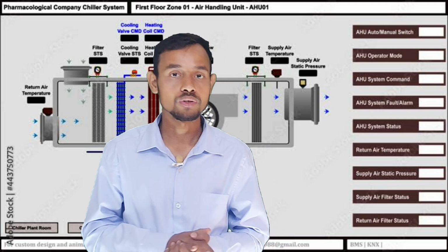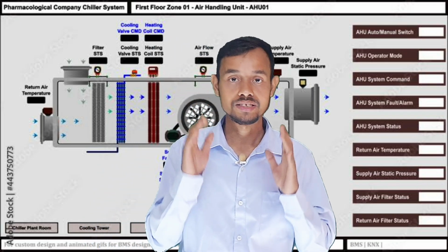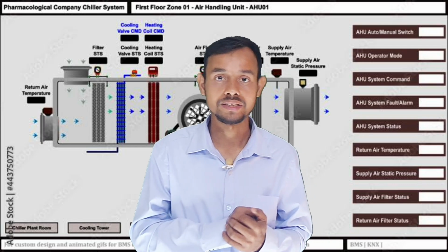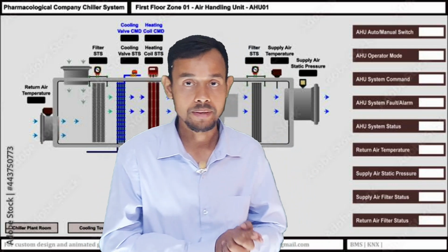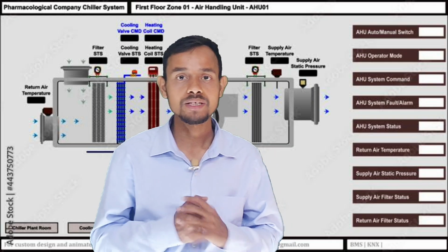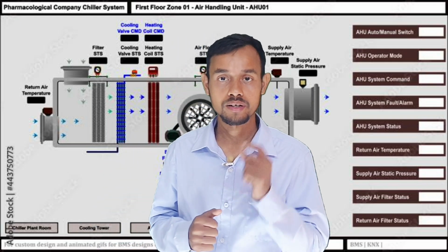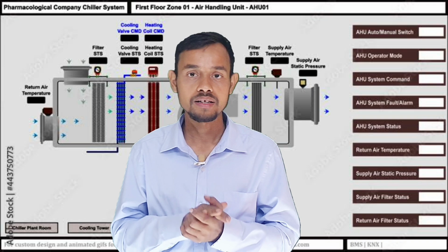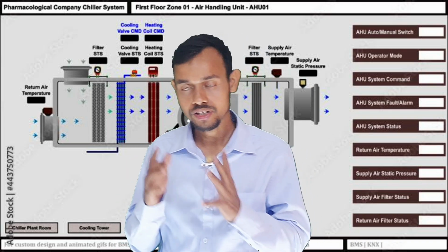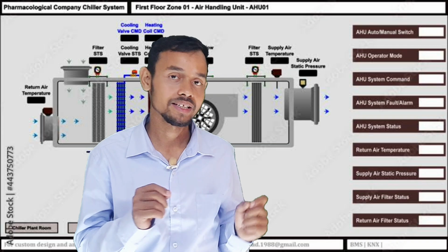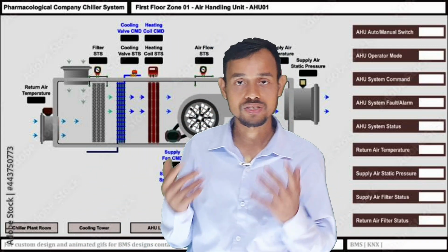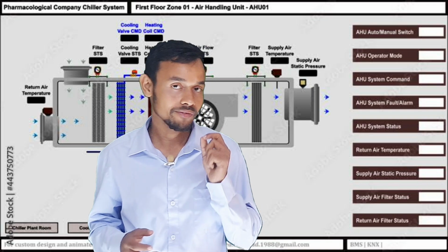The user can control all HVAC systems by changing temperature, humidity and many other functions from the BMS control room. BMS shows an alarm on the computer if there is any fault in the HVAC equipment and alerts the user, like when an HVAC filter is dirty. So BMS alarms that your filter is dirty, the DPS sensor, the differential pressure switch, is open.